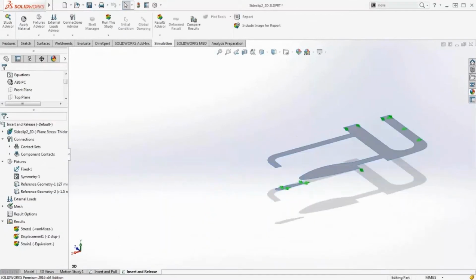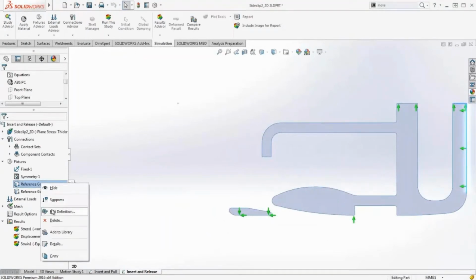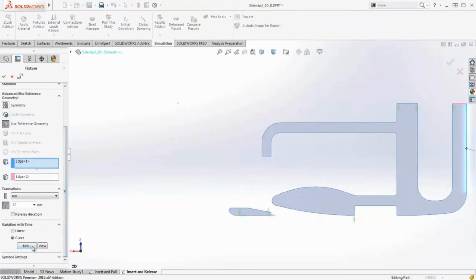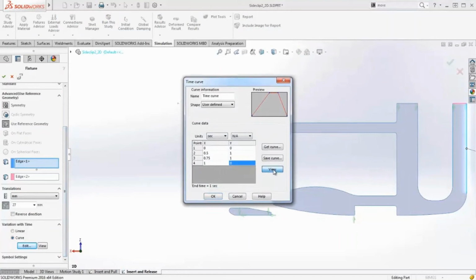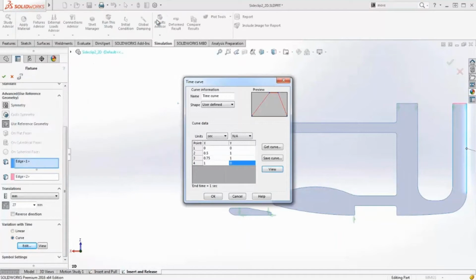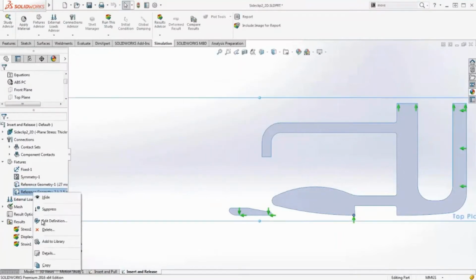In this side release clip, it's important to verify the performance of the clip for the insertion and release operations. Verifying the operation in 2016 is a breeze with a new intermittent fixture capability. The fixture that inserts and removes the clip pushes it over half a second, holds it in the inserted position briefly, and then pulls the clip back out in the final quarter second.